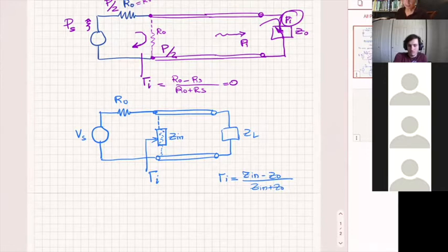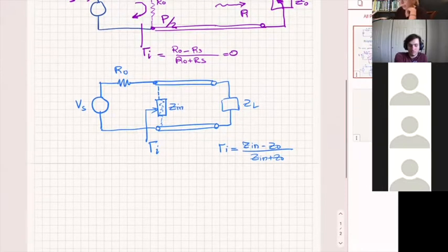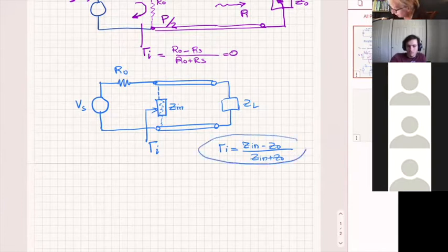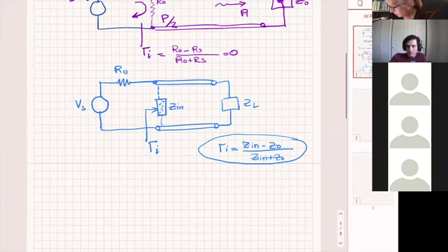If that is the case, how much is the real power that eventually goes into the line? If right at the beginning of the line, where the line connects, there is already a reflection, and this reflection may not be just a real number but maybe a complex number, how much is the power that eventually gets into the line and goes into your resistor, your impedance, at the end?